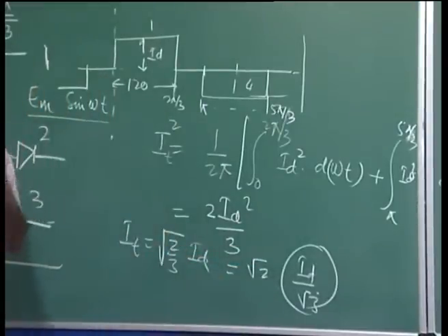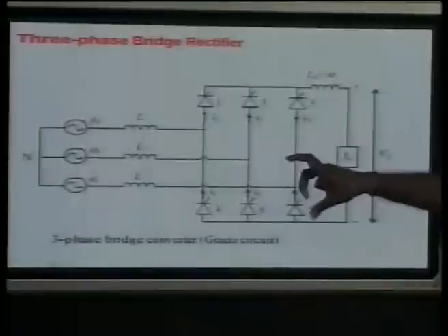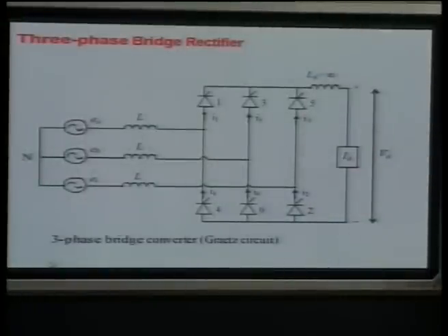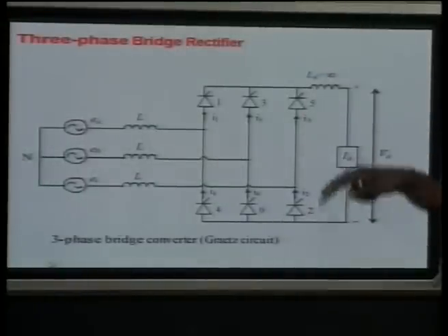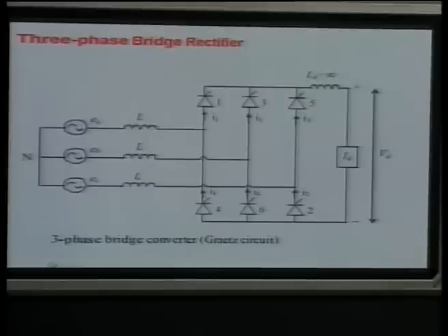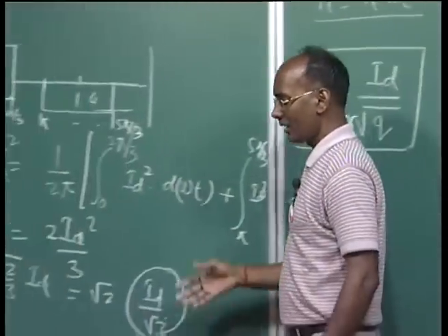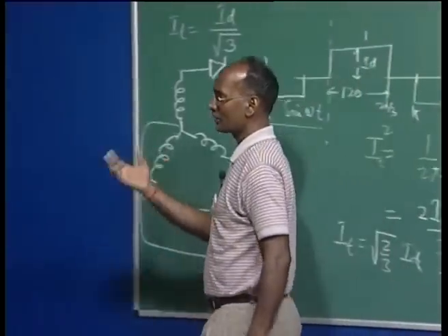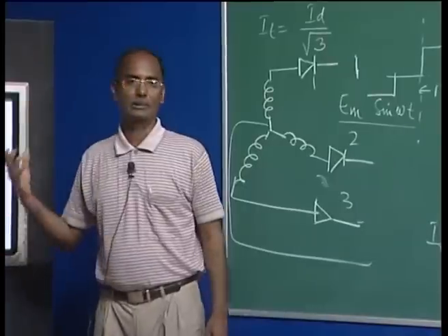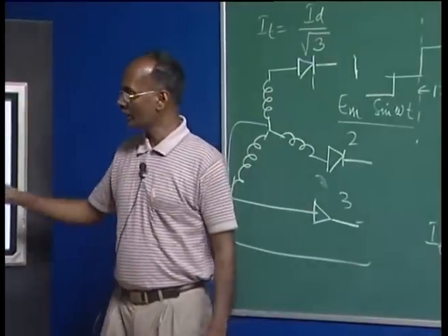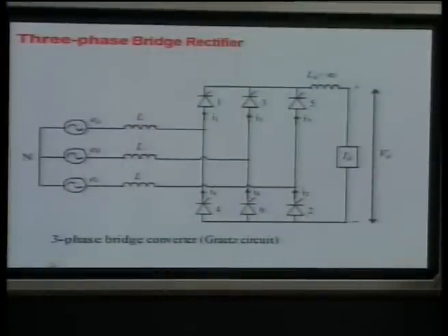So, by arranging in such a way, this bridge rectifier, also known as the Graetz circuit, is the best popular combination for converter applications, both rectifier as well as inverter. So, with this whole analysis, now we have also arrived that this bridge converter is the best suitable for our HVDC application as well, because we are getting all our desired features for our converter configurations.